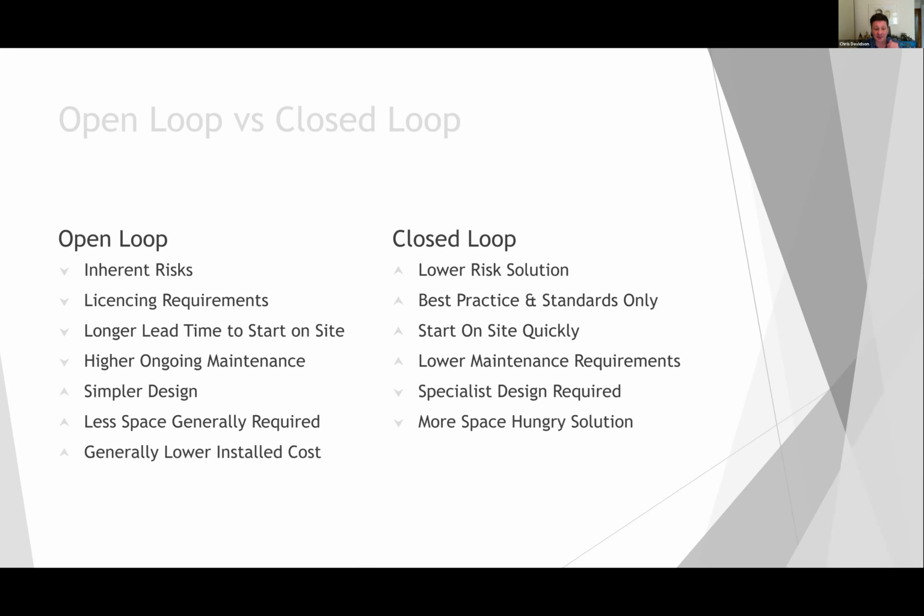Generally also, open loop is a lower installed cost. When you do the sums, when you look at feasibility studies, as I do every day on these systems, it generally comes out that open loop is a cheaper solution. The quantum of that can vary, could be 10%, could be 20%. Those are the kind of values that you would see in terms of savings of open loop systems over closed loop systems. So closed loop systems are generally slightly more expensive. And then finally, there is a point I'm going to make on both sides. Both can be more efficient.